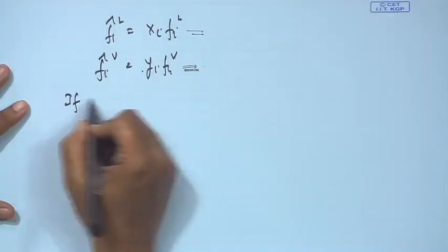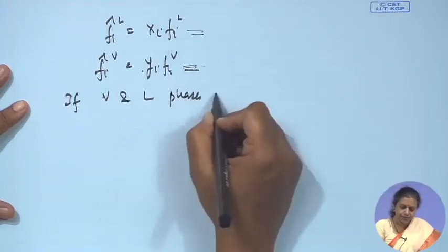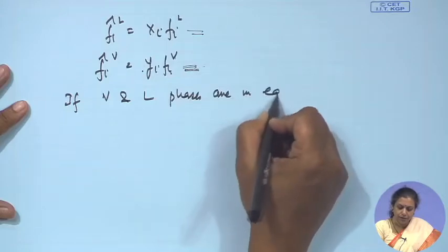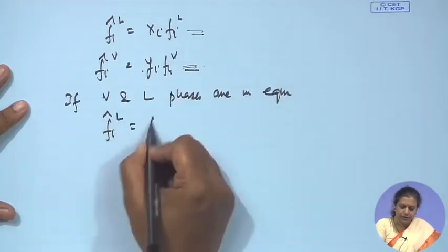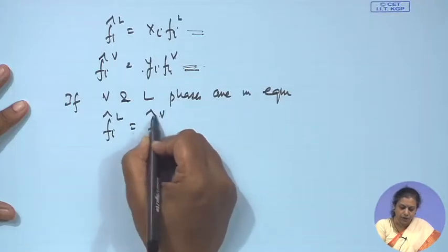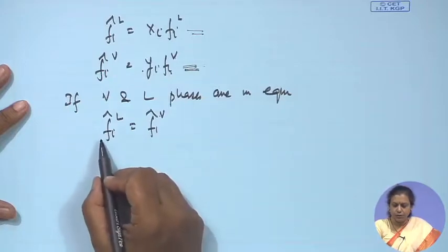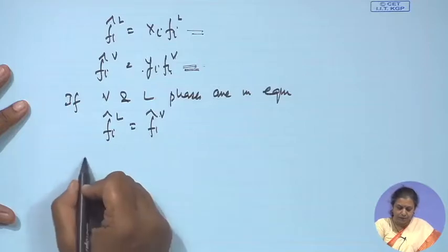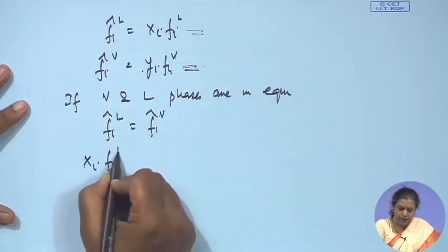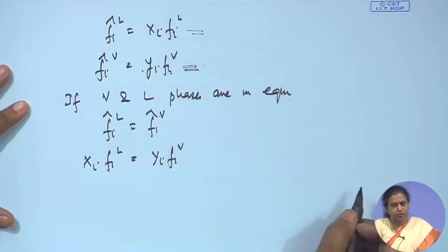If I assume that the vapor and the liquid phases are in equilibrium, when is it possible? We have already framed the conditions of equilibrium for the two phases in terms of fugacity. So, fugacity of each component must be same in all the phases, or in other words this should apply. If we write it down in terms of pure components, this particular function should apply.